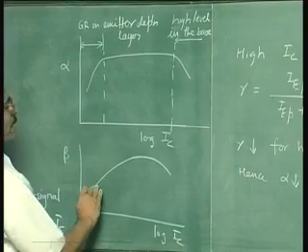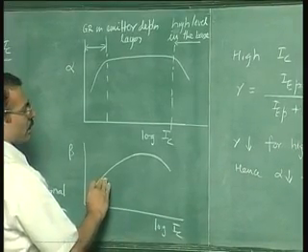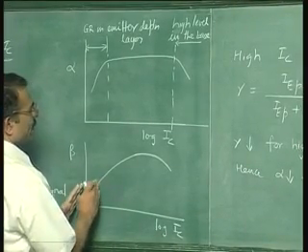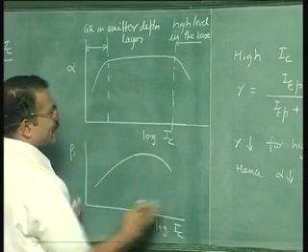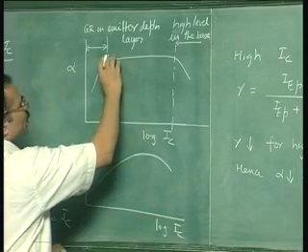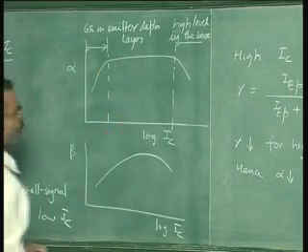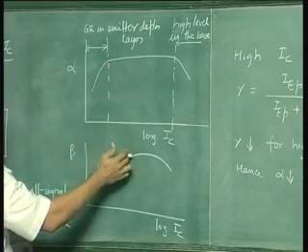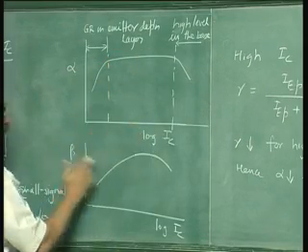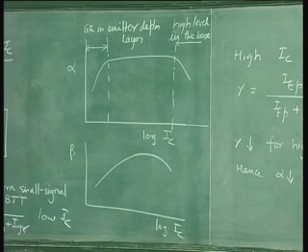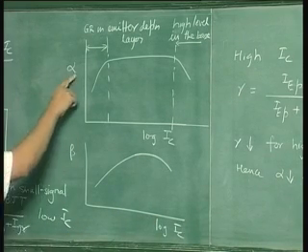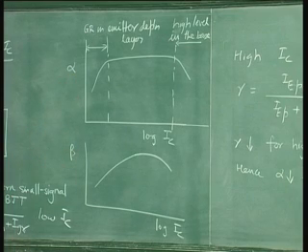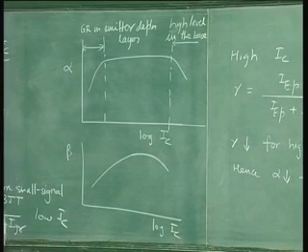So the change in beta appears everywhere on this IC axis, although alpha appears to be fairly constant over a wide range. This difference in shapes of alpha versus IC and beta versus IC has to do with the fact that beta is very sensitive to change in alpha. So even for a small change in alpha, there is a large change in beta. I leave it to you as an exercise to show.